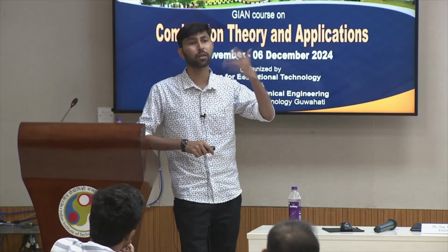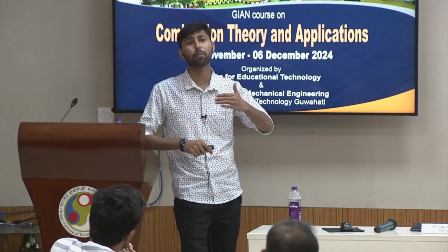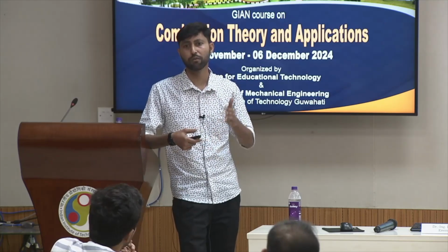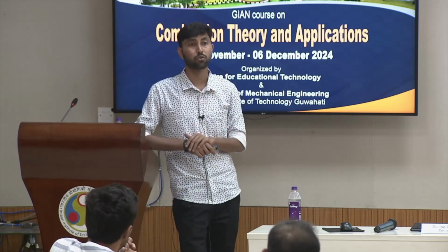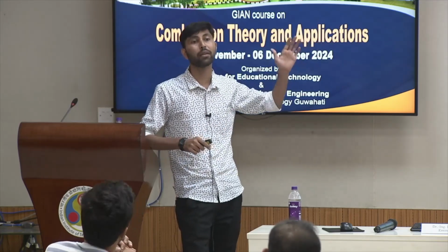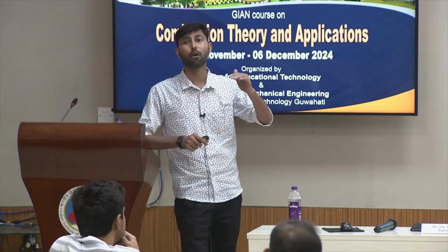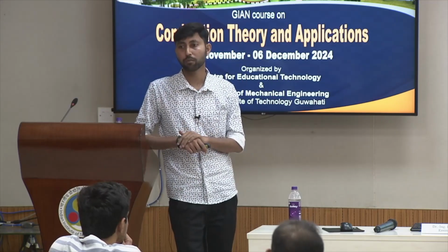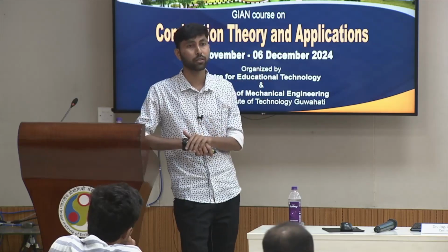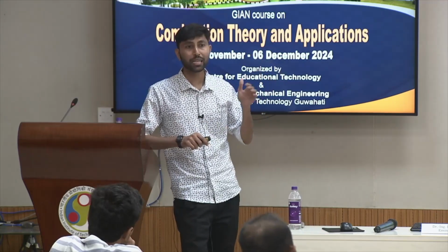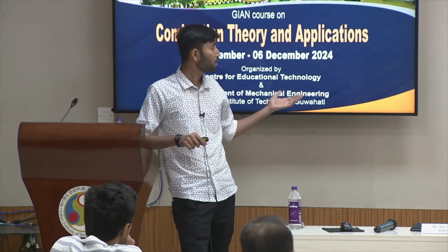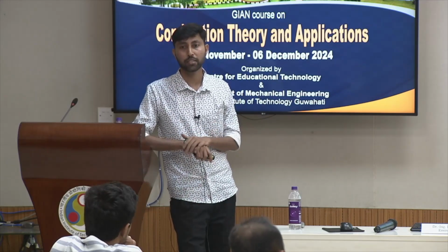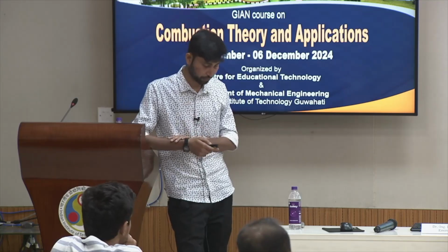If the pressure drop increases, we need to supply more pumping power, so that is the loss, and efficiency will reduce. So we need to concentrate on that factor also. My research work was mainly focused on that, to optimize this increased pressure drop with higher heat transfer rate. In order to do that, I have used the application of the second law of thermodynamics, that is exergy and entropy generation analysis, that I have performed.